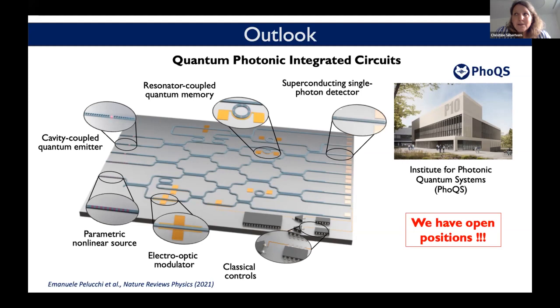Now, Chi3 nonlinearities are typically much weaker. And one thing you can't do with Chi3 nonlinearities, as far as I know, not efficiently, is modulation. And these modulators are extremely important, as I demonstrated. If you want fast modulators, fast feed forward, fast switching of bases, you will need Chi2.